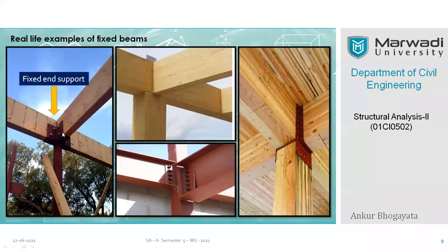So here there are bolts which are used. You can see there is a channel-like platform within which you can sit your joist, and then when you offer bolts, always remember you should use minimum 2 bolts to ensure the fixity.